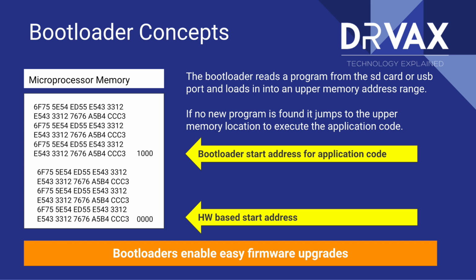There's a complex picture here about how that works. I have a video on the channel about loading Marlin version 2 into a computer that goes through this in detail. But basically, as I indicated, your computer goes to a particular address called address 0 to start, and it loads any new software it finds into, let's say, address 1000. Those would be hex numbers. Those addresses are made up. But basically, a bootloader allows you to load new software. It's a really important thing I would look for in your 3D printer.